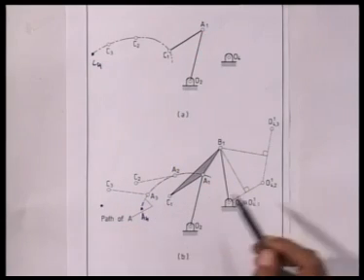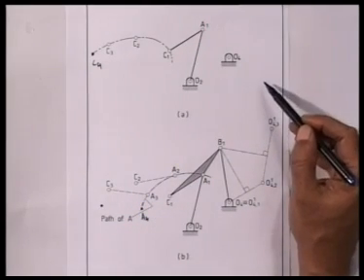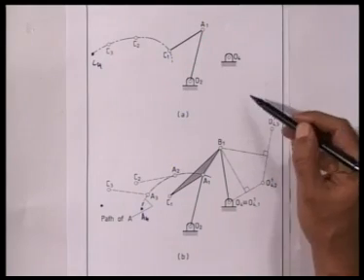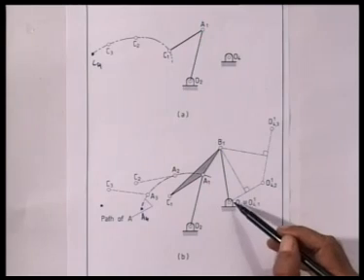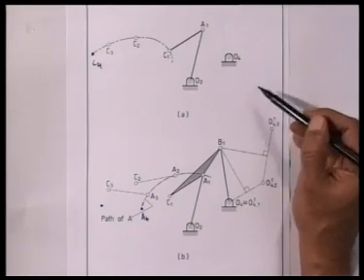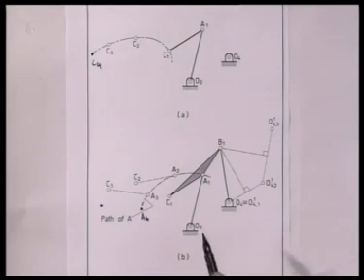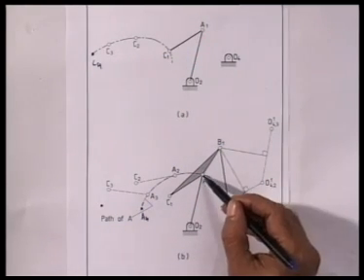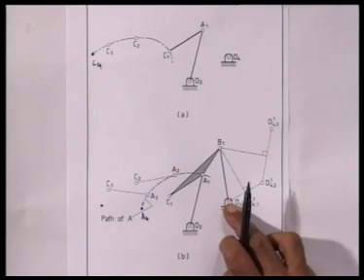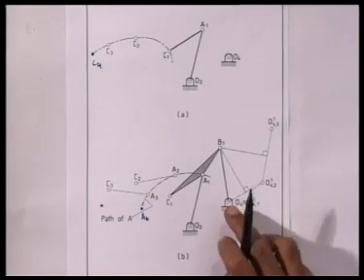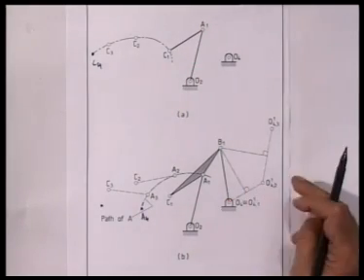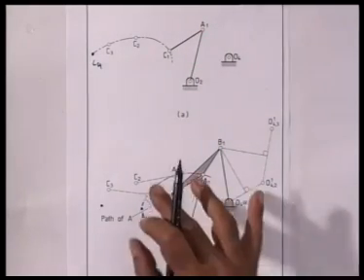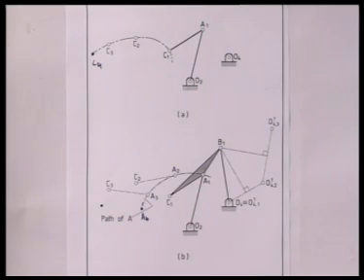But the inverted position O4 would have been an arbitrary point, and there is no guarantee that one can draw a circle through such 4 positions of O4. So, in the point position reduction, we choose O2 and A1 arbitrarily, but O4 I do not choose arbitrarily. O4 we locate in such a way that 2 of these four inverted positions coincide. I shall explain this with the help of an example.